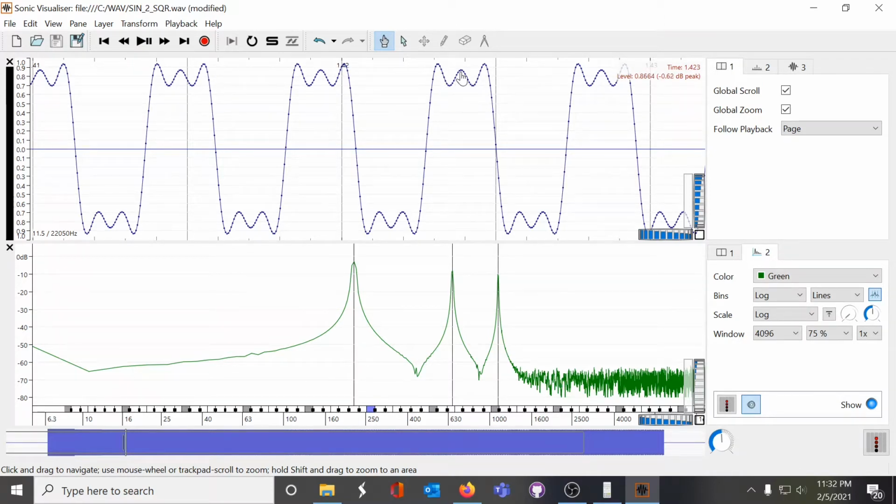We can see that the fifth would have a peak during the valley of the third, but the peak occurs simultaneously with the fundamental. Anyway, you can see that they have added up and we're starting to become more square on top. Same thing in the valley. You'll also notice that the skirts of this waveform are becoming steeper.